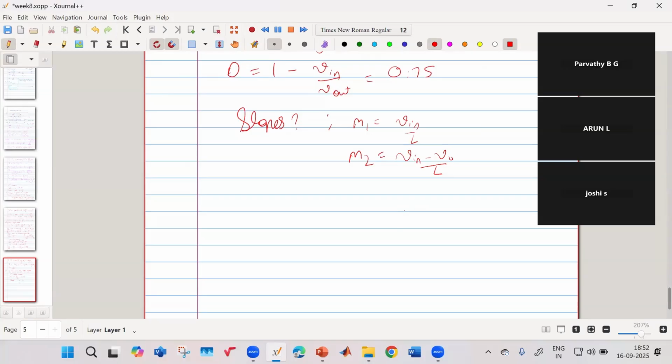So let us look at it. Let's see the boost converter. This is your boost converter. You have your input over here, your inductor over here. This is your main switch, which is the MOSFET. This would be your diode, right? This is your capacitor, and this is your load resistor. This is your V0.